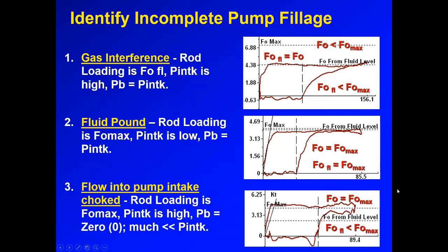Now, there are conditions or problems downhole that will make the pump not be full of fluid, and that is detrimental to the system efficiency. We are installing a pumping unit, rods, and pump to make the plunger move, but the pump is not full of liquid. We're doing that to displace liquid. And if the chamber is not full of liquid, we are losing system efficiency because we're spending a lot of energy to move a plunger, and the plunger is not displacing fluids to surface.